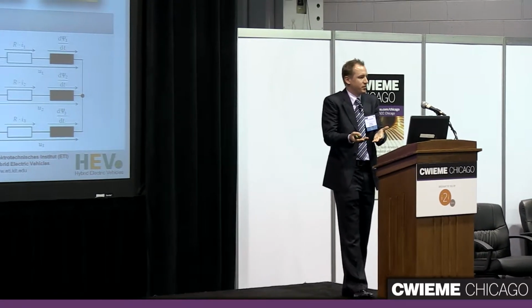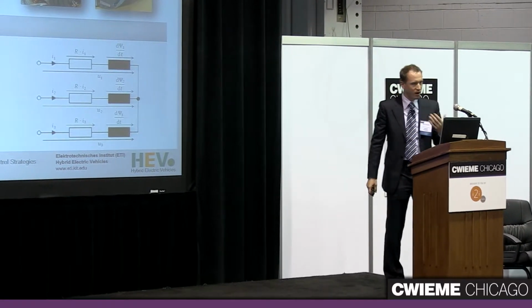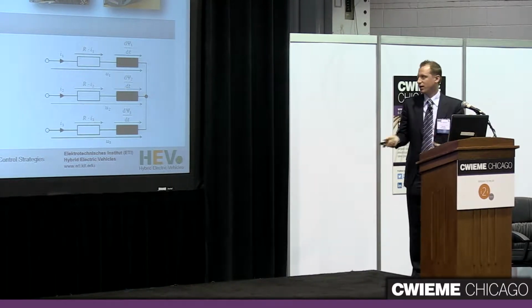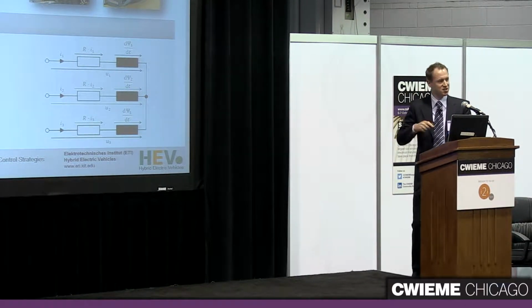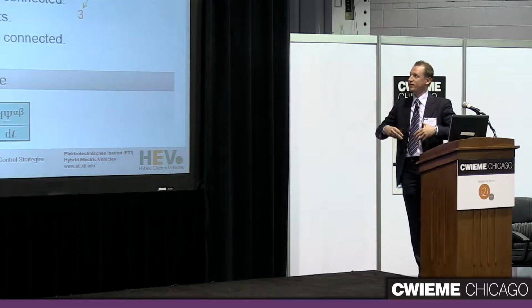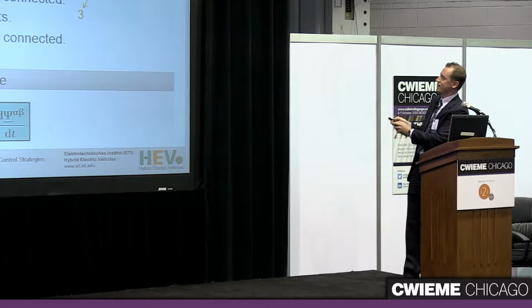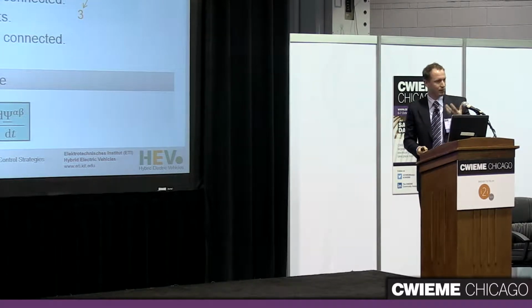And you'll have this equation for 3 coils, because you have 3 coils in the machine. But it would be a lot better if you would only have 2 equations, right? It's just easier if you just have to deal with 2, and this is possible. You don't lose any information if you reduce the order of this system by 1, and this is done by a transformation, and that is called alpha-beta transformation. The equation is given here, not so important. Maybe look at this little sketch right here to understand what we actually do.